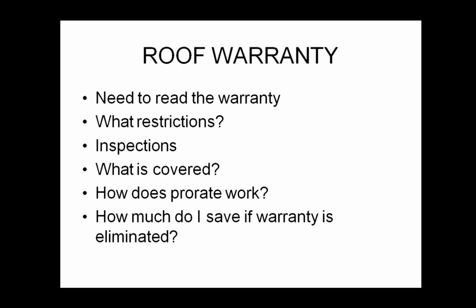And basically you need to ensure that the material or the roofing system that you use has a warranty that meets your specifications. Okay, each of these kind of roofs have a different length of warranty time. Like I said, the typical roofing shingle on a house would have something like a 25-year warranty. Other systems have longer warranties, and sometimes the warranties are dependent on the locations and if they're installed by a certified applier of that material or of that system. Right. So make sure you understand the material and you read all the fine print about what would void that warranty, because believe me, there's a lot of things that would.